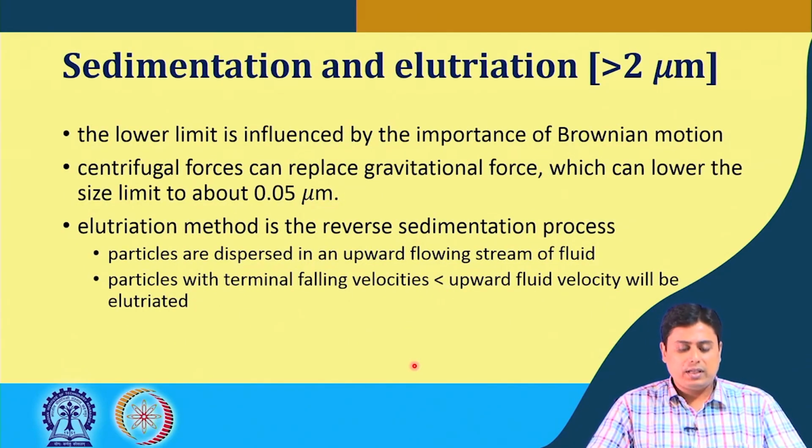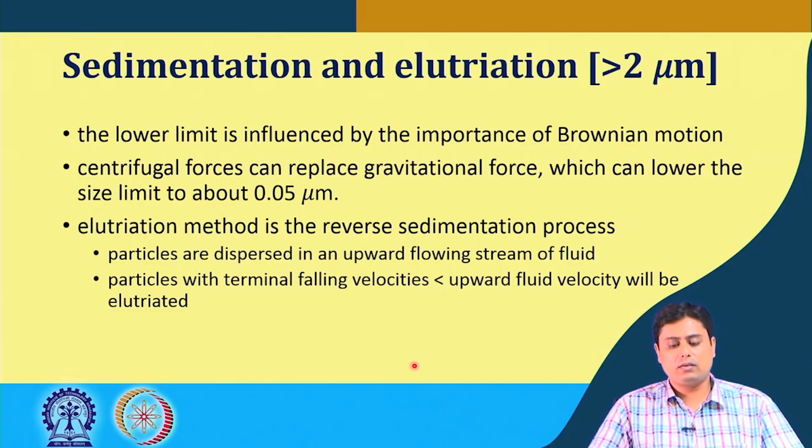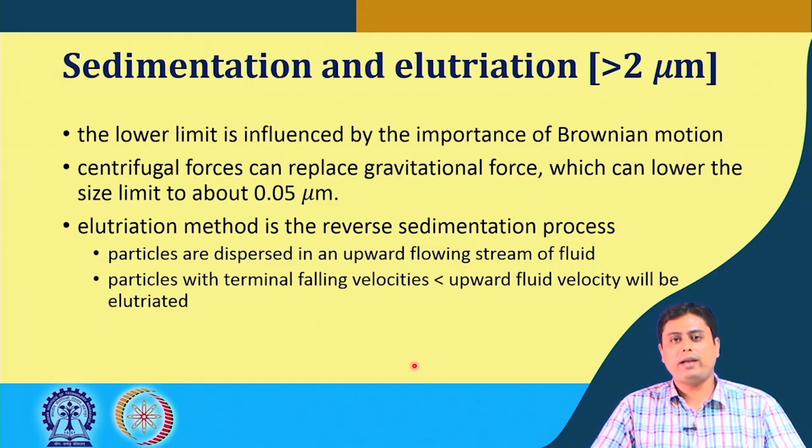The lower limit in this case is influenced by the importance of Brownian motion, because as we decrease the particle size, Brownian motion becomes dominant. So, the lower limit we have to set accordingly, or we can determine based on the fluid property that we chose when these particles are sedimenting.